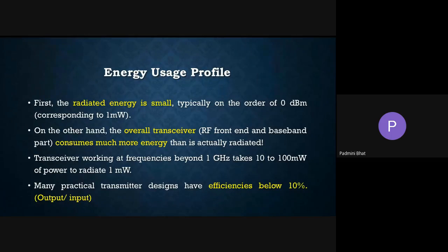This is one very common design aspect. Antenna height is proportional to the wavelength of the data we are sending. That is why the wavelength has to be converted. If you are using a voice signal or anything, you have to modulate it to the wavelength in which the antenna can propagate correctly.